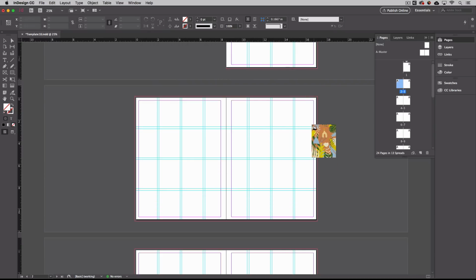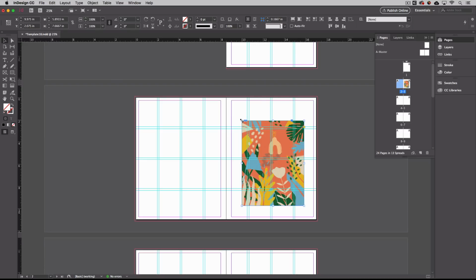You'll see this little placement icon. And once I click it, it will open it to scale. So this is the same size that it was created in Photoshop. Now, if you want to make the guides disappear, remember you hit Command semicolon and it'll turn them on and off.